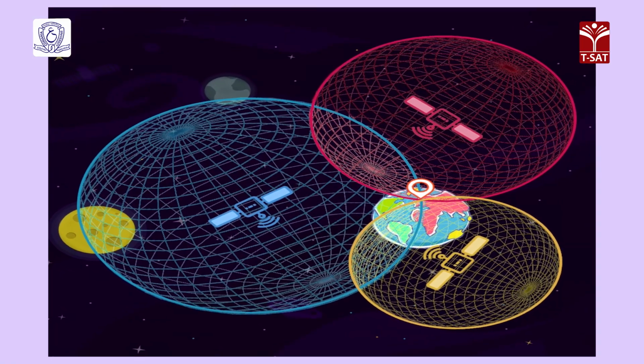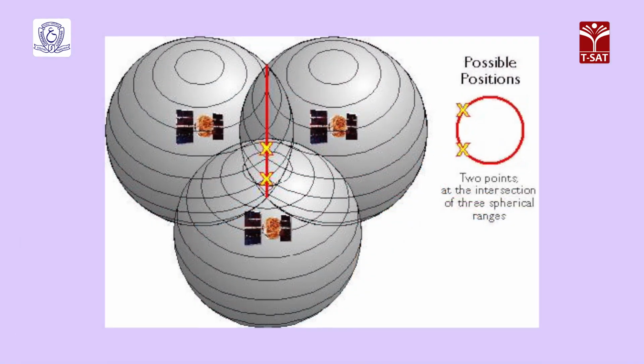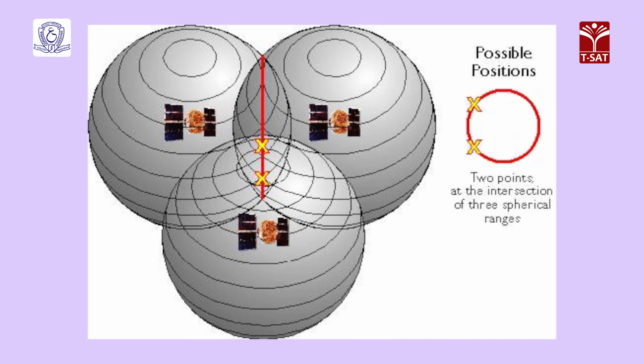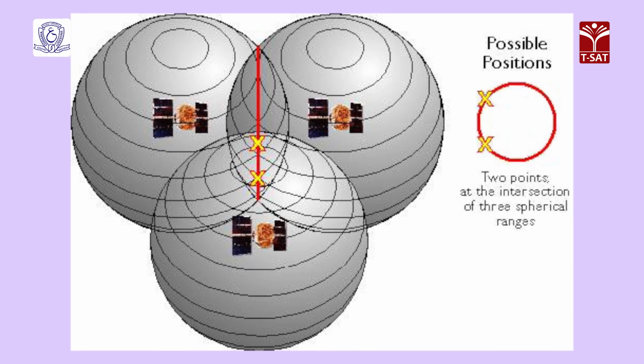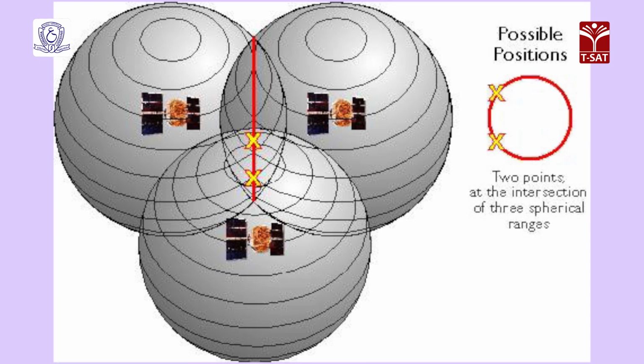When a third satellite becomes visible, the GPS receiver can establish its position as being at one of the 2 points on the previously derived circle where the third satellite sphere intersects it. So, whilst position fixing is possible, it is unreliable unless it is assumed that the receiver is at sea level on the surface of the earth, because it is almost certain that only one of the 2 derived points would be near to the surface of the earth. So, fixing is possible, but only in 2 dimensions, 2D fixing in latitude and longitude.